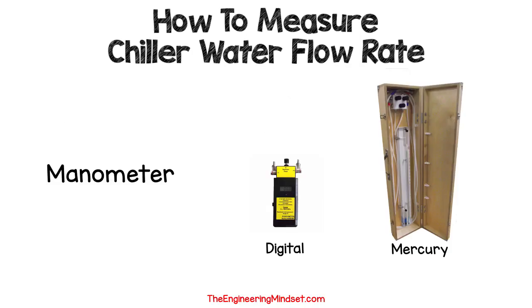We also need a tool to measure the flow rate with, so for this we need a special manometer which can suit the pressure difference of the system. You can buy compact digital versions which are easier to transport and more precise. However, I'm going to use an older mercury based manometer to measure the flow rate simply because that's all I had available at the time.